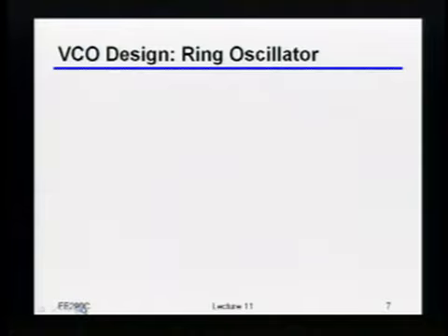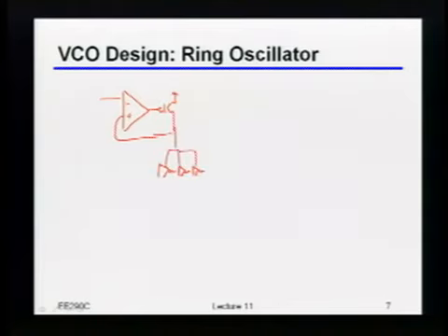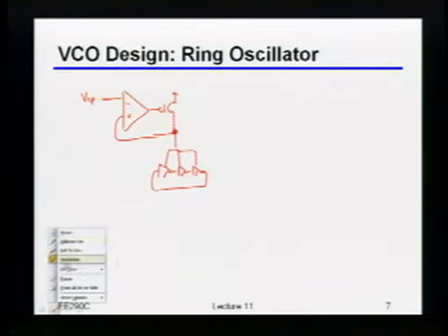But it turns out that in a lot of contexts, like we just drew, and for reasons that I'll explain shortly, one of the fairly popular architectures these days is to use a supply regulator to set the supply voltage of some ring oscillator, and then use that ring oscillator to act as your frequency source. So this would be coming from the charge pump voltage, this would be your internal power supply voltage, and then conceptually this would be the oscillator, and the output would be right here.